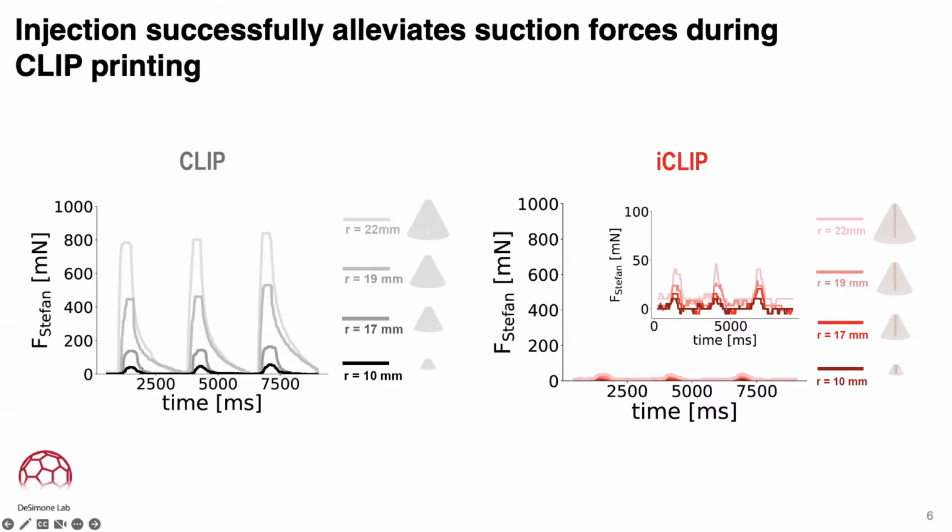In the injection process, as shown to the right, such forces, while they're not disappeared, are significantly less. For the same parts with the same cross-sectional area, injection reduces such suction forces by orders of magnitude.